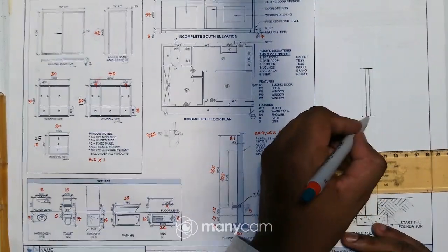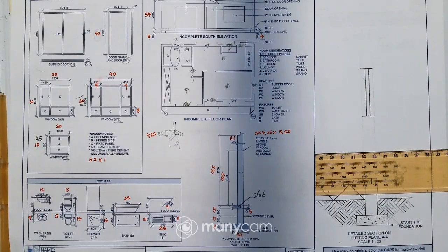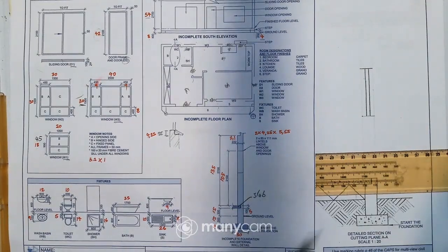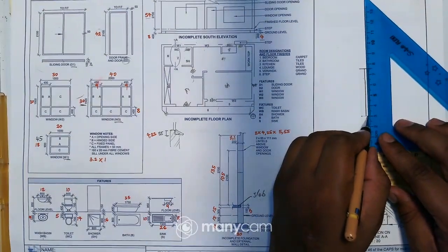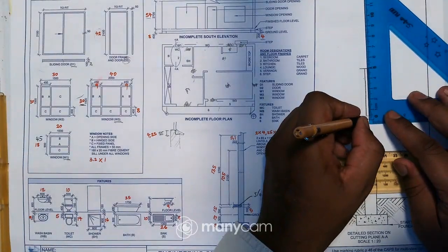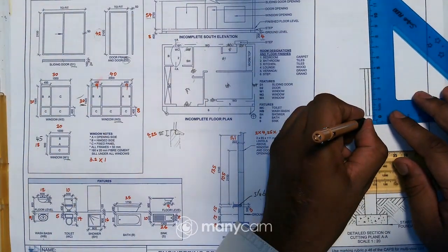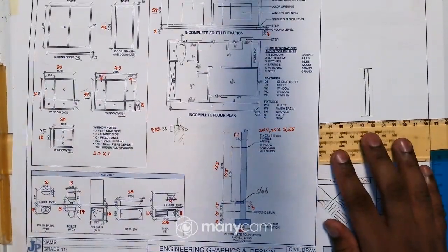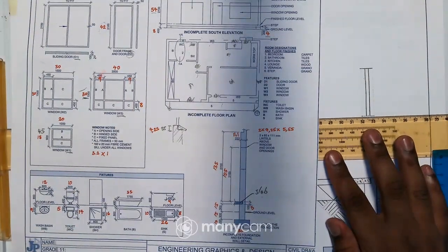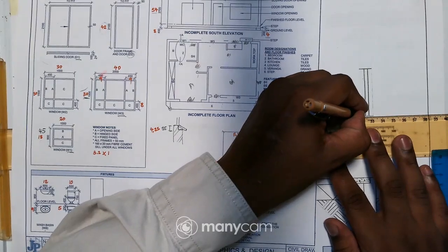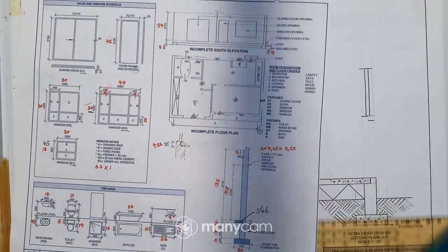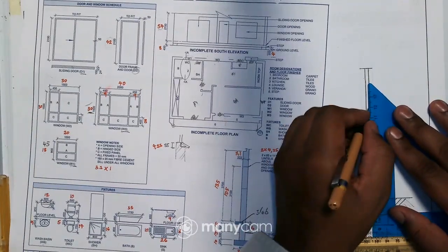So I'll just draw the step right over there. Okay, so let me just draw it there. So I have the center point there. I just draw a construction line and measure 4.25. So I can just make it 4 like that, and then draw a line there, even there. You can just draw a line like that. Okay, so now I do have my step there.